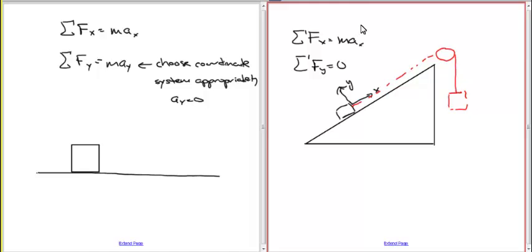If you go back to chapter 4, as far as the videos are concerned, you'll see all those different combinations of things happening, and you do free body diagrams, and then you sum the forces for the two bodies. In this case, this example here, the sum of the forces in the x direction is going to be equal to the tension pulling like this on the cable, and then you're going to have friction force pushing down, and you're going to have the weight, which you break up into your two components,